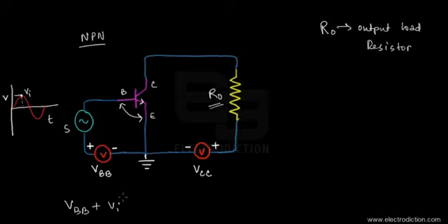This voltage falling across the base and emitter terminals would forward bias the emitter junction and cause an input current, which is also quite small in magnitude, to enter through the base region.